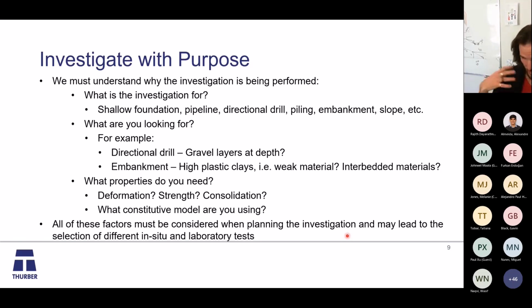We also need to be thinking about how we're going to do the analysis. So what properties might I need if I'm doing deformation or strength or looking at consolidation? Different constitutive models require different tests. And we really need to consider all these factors when we're planning the investigation. And we may select different lab tests and in situ tests.